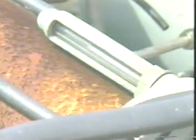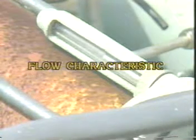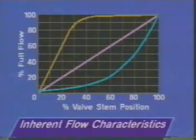In addition to affecting valve capacity for given conditions, trim design will affect how the valve capacity changes as the valve plug moves throughout its travel. The relationship between valve capacity and valve travel is known as the flow characteristic of the valve. Many valves are not linear in nature. Trims are designed or characterized in order to meet the large variety of control application needs. For example, most control loops have some characteristic nonlinearity that can be compensated for with a proper control valve trim selection. Charts like this are used to illustrate the various control valve flow characteristics.